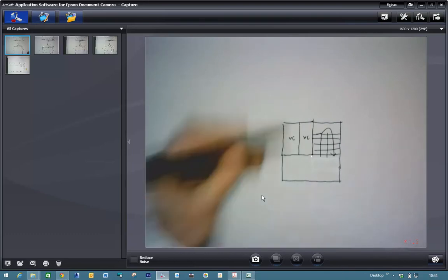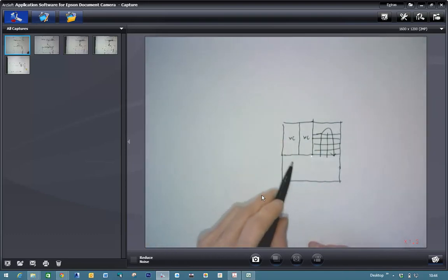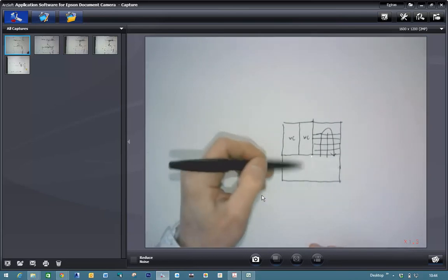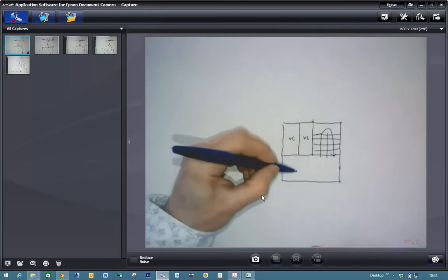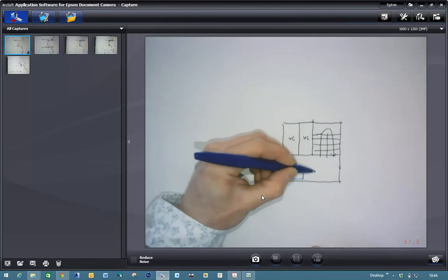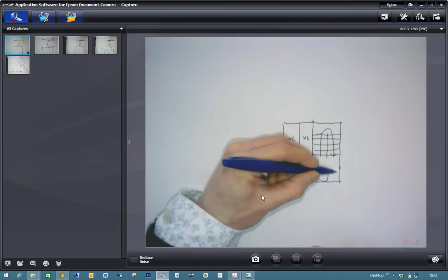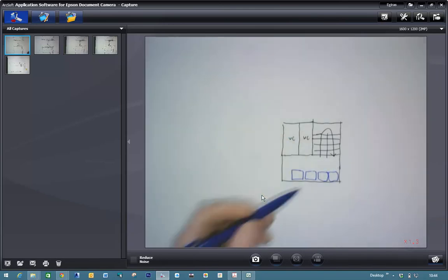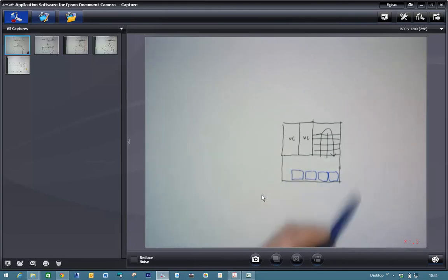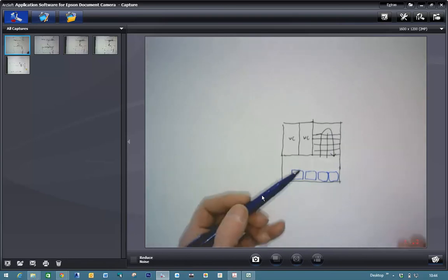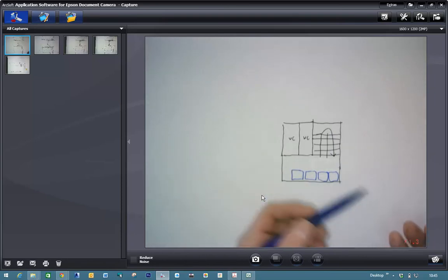So for example, you could here have a much more generous sort of lobby, which is good because you can mill about when you're going to the toilet and waiting for people. Gets you into the stair, and it also means you can potentially have your refuges in here. And if it's a big building, you'd want more than one. So rather than that sort of refuge being crammed into the top of the stair, and the person in the wheelchair has to sit and watch everybody escaping, often you might as well build it into some circulation space.